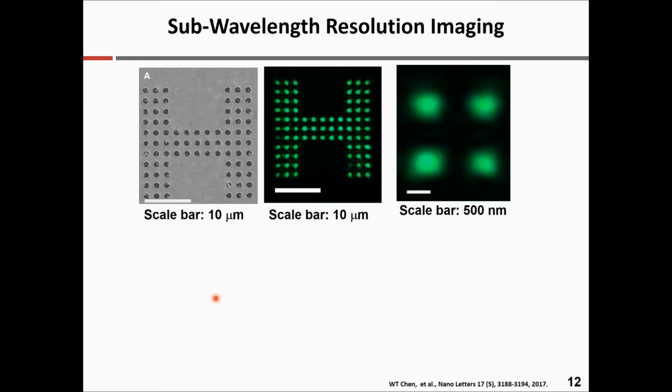We just wanted to push it slightly more to see what's the minimum resolution that we can get. We made our own custom resolution chart. It's an array of holes fabricated by focused ion beam on gold-coated glass. The minimum gap here is 800 nanometer.